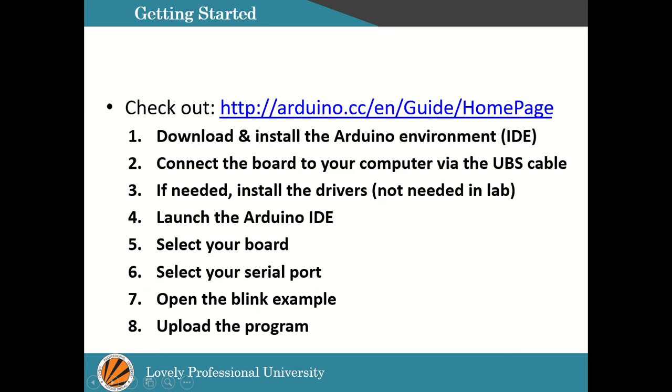Then you can launch the Arduino IDE. Then you can select the board. We have a number of boards, so we need to select the Arduino board. I'll be showing you in the next slides. Then you need to select your serial port. Then you can start with the basic blink example, upload the code, and you are ready to go.